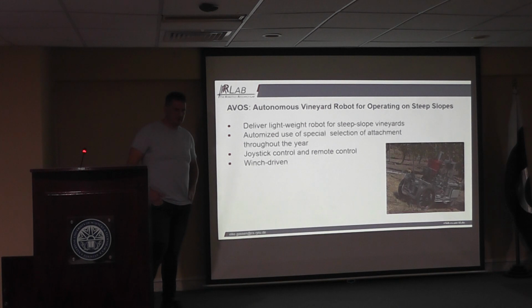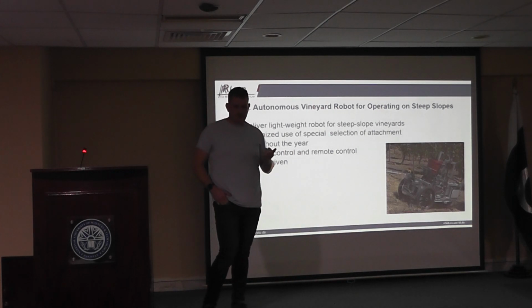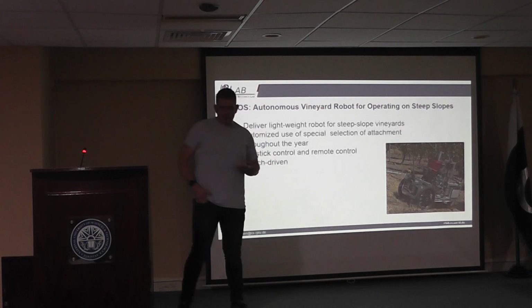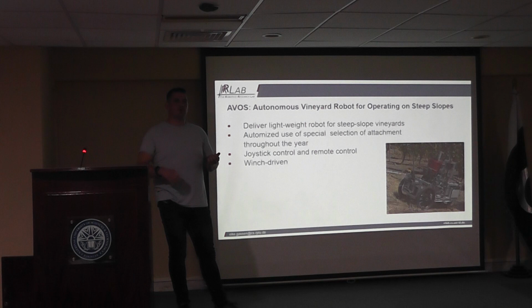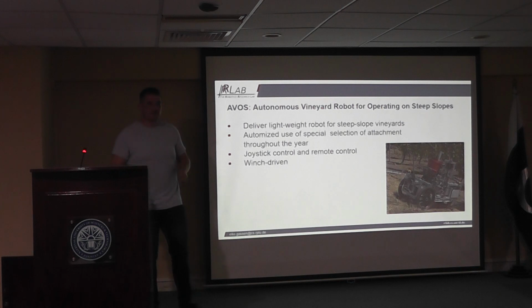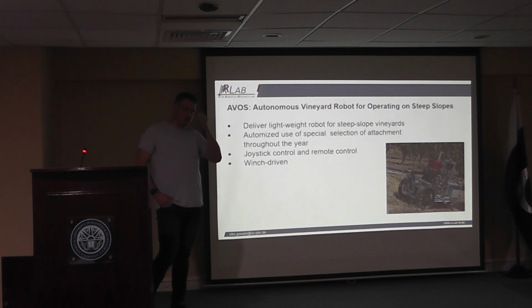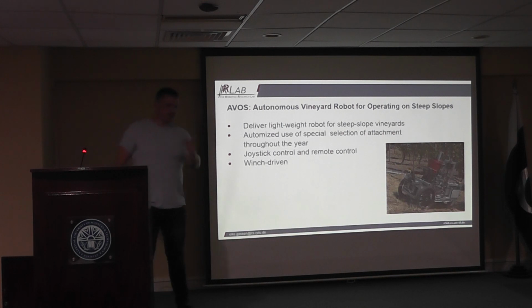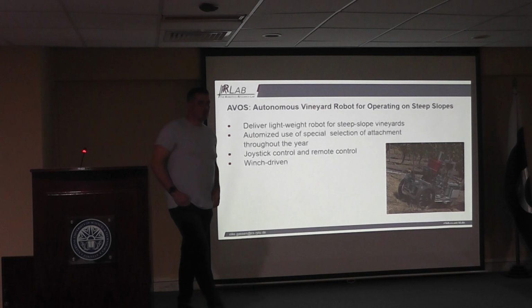Yeah, exactly. So we have two ways. You can do it in an autonomous way by this steering motor, which puts pressure on the hydraulic cylinder, and we also have the possibility to steer by hand, which does the same, but of course manual steering is limited. You cannot steer very far, only within a limit. So you mean the angle of the wheel? Yeah, this is it.